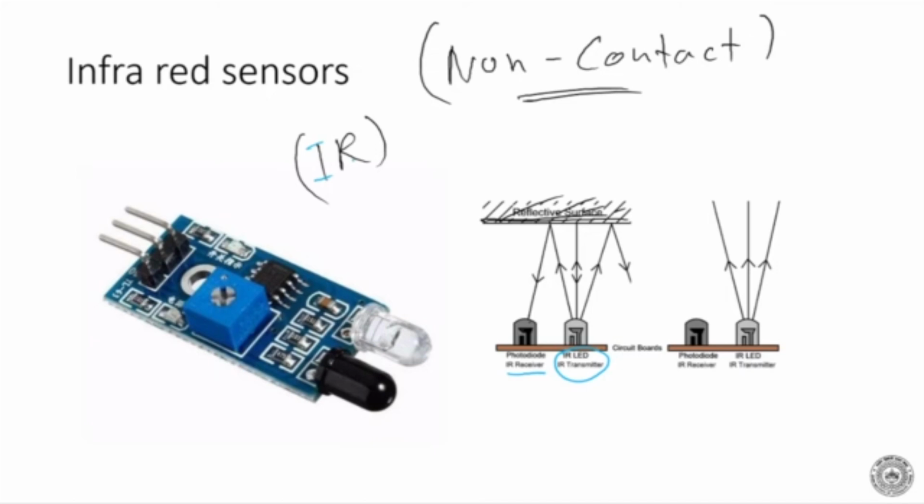Now, you can see ultrasonic sensors and IR are non-contact type. They don't touch; from far they can make out. So the robot can enforce a behavior simply when it gets the signal input. If the program receives the signal that there is something in front, it can immediately change its behavior. Okay, it can try and avoid the obstacle.